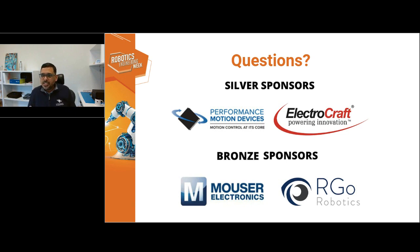There's a lot of customization that happens in terms of the firmware features, or they want unique I/O, because there's only X amount of I/O, 8 digital I/O and analog I/O in the drive. They want to do unique things like a brake for safety, where the brake ties in with other functions. So there's a lot of unique capability that they want. If they don't have their own host, we can do all that customization in our drive.